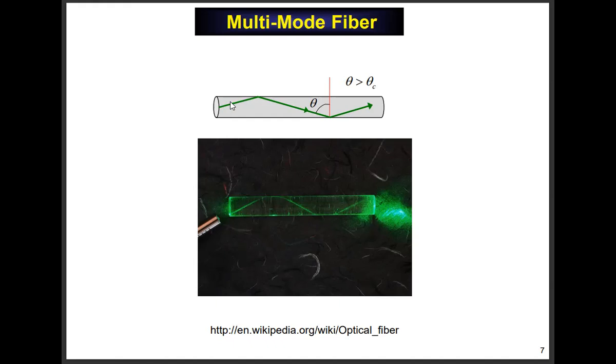Okay, so visualize, if you would then, this beam coming along here, and it's bouncing around internally at an angle theta from vertical. And remember, if you go this way from inside the rod, and then there's air out here, this is where the critical angle effect applies, right? Going from denser to less dense. So there's a critical angle here. Now, what if this angle theta is greater than the critical angle? This beam is going to be reflected here. And you remember what happens if you're beyond the critical angle? 100% of the power gets reflected, right? Remember that? Now, let me remind you, does it mean there are no fields out here? There's that thing called alpha ZT in the notes.